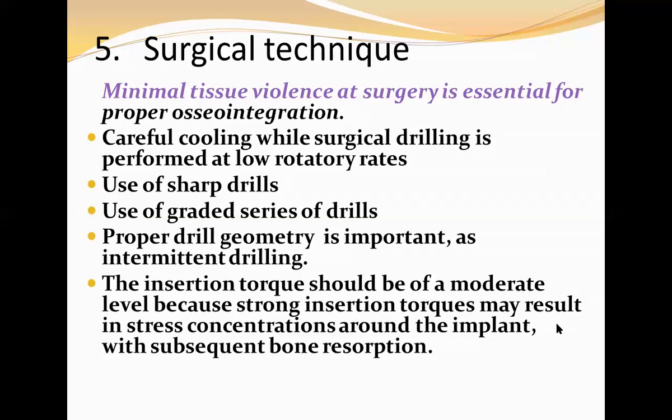But if you don't have internal cooling facility, but you have to be very careful कि आपने intermittent drilling करनी है, once in a while नहीं करनी. The speed of your drill must be enough. Normally 1000 RPM is recommended there. तो वो आप स्पीड ज्यादा रखेंगे तो लेस हीट जनरेशन होगी, आपकी ड्रिल शार्प होनी चाहिए. इसके अलावा जो आपकी ड्रिलिंग जो है वो उसका सीक्वेंस इट हैज टू बी प्रॉपर.